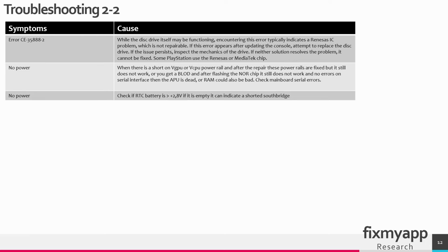When you see this error code and your Blu-ray drive is fully functional but it doesn't work, it cannot read any data or something, then this could indicate a problem with Renesas IC, and this is an IC that you cannot replace because they are married to the board.